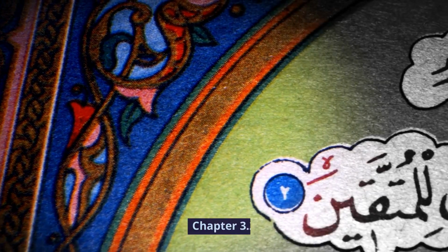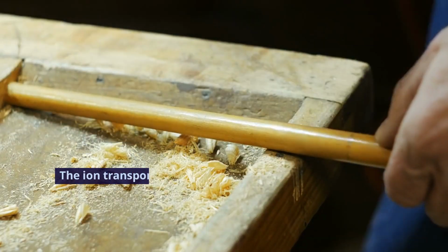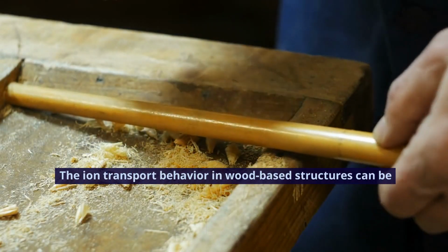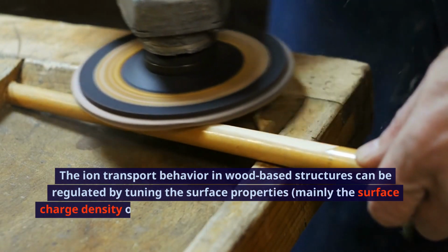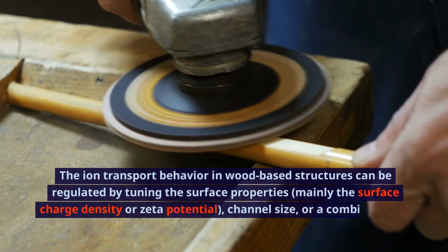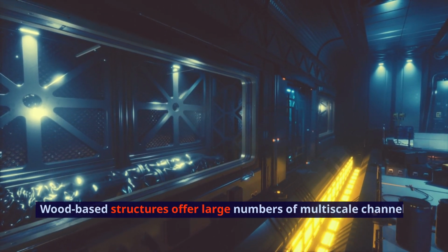Chapter 3.2. Regulation of ion transport in wood-based structures. The ion transport behavior in wood-based structures can be regulated by tuning the surface properties, mainly the surface charge density or zeta potential, channel size, or a combination of both. Wood-based structures offer large numbers of multi-scale channels for ion transport.